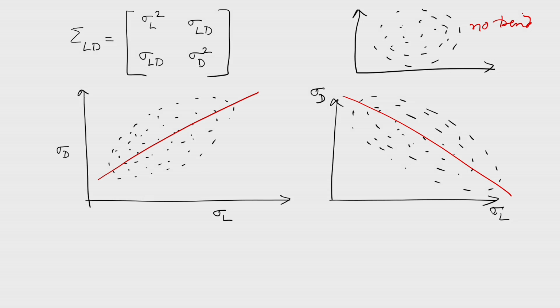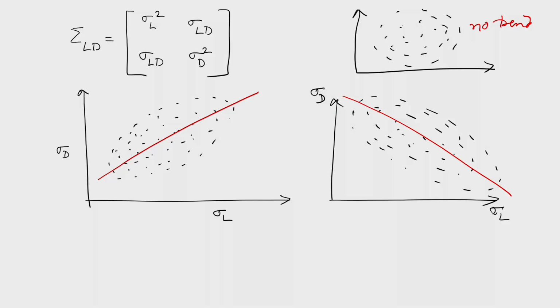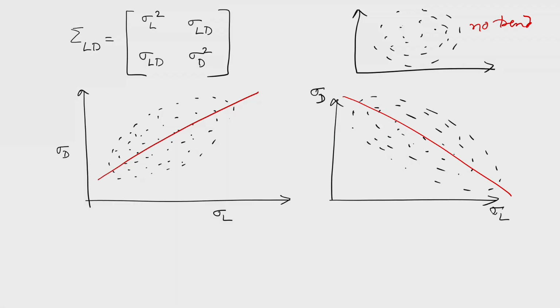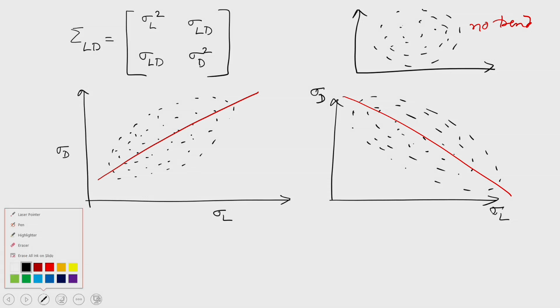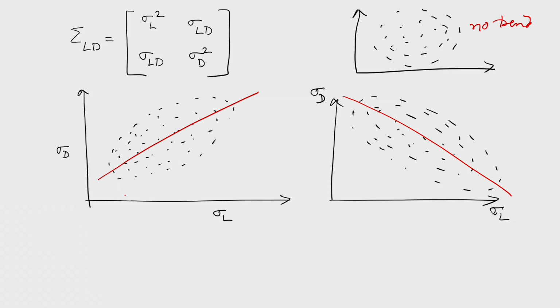So, in these two cases where I can observe the trend, I can say one thing, that there could be a relationship between L and D, that means their errors are correlated. So, I can find the correlation between the two, that is the coefficient of correlation. Apart from that, I have one more query: what is the maximum error? Because it is an elliptical shape, I can see that this error is maximum here, and here I can see that this error is minimum, which is across this.